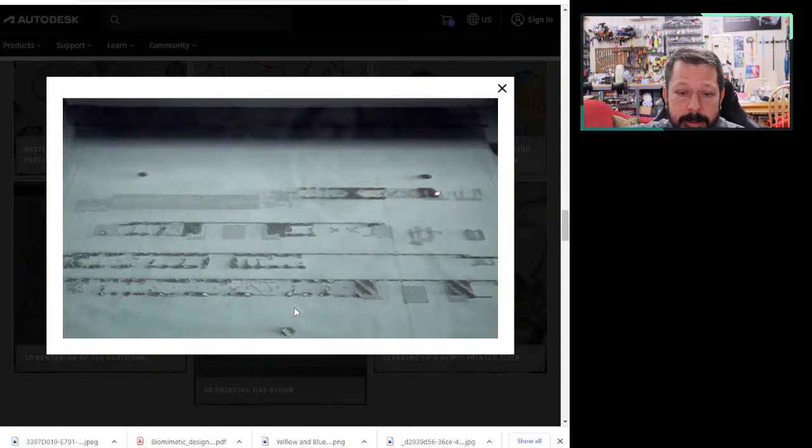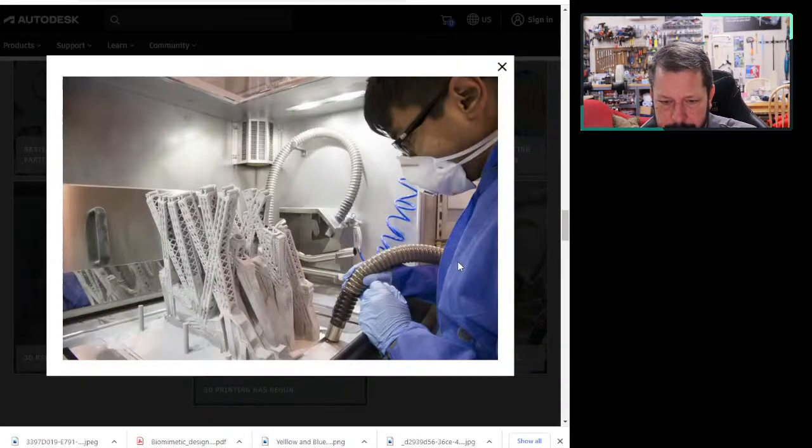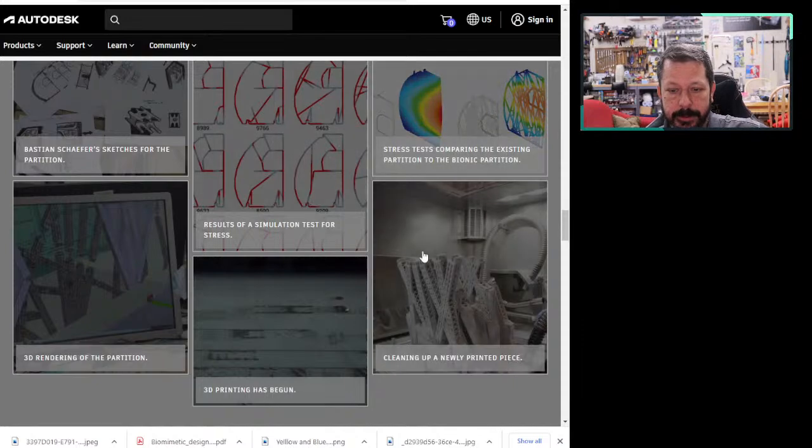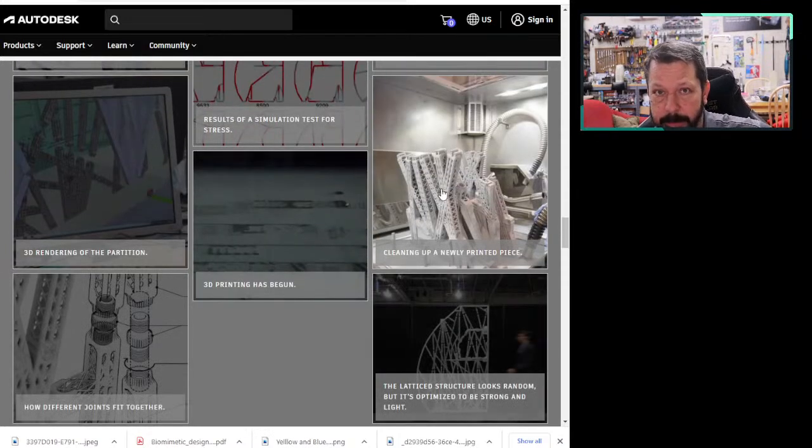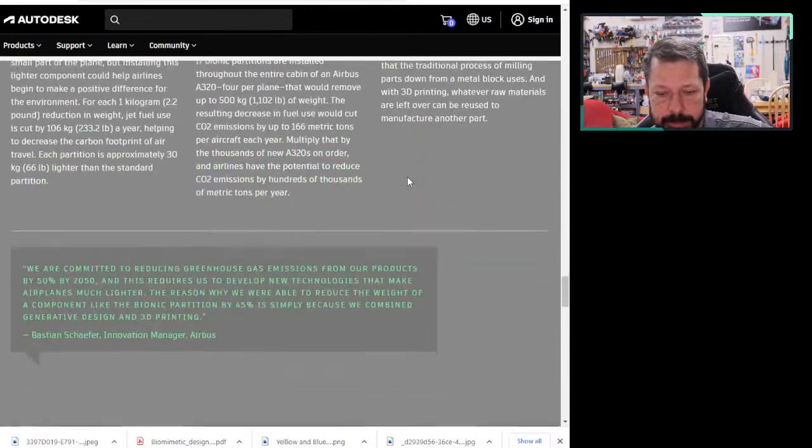In this process, there is no waste. All the unused, unfused powder is filtered and sifted and used again. So you don't have any waste unless there is a little bit of support material. Let's see if they had supports in here. I don't know. Looks like maybe right in that area might be a support. But they generally just use the powder itself as the support because it's still there. It's just not hardened, not fused. So there is very minimal waste of supports. It can have supports, but it's minimal.